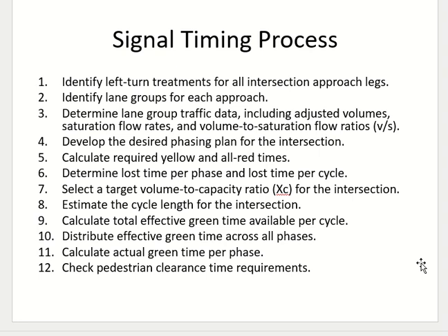If there are 2 lanes in one lane group, both of them have the same movement, which is in the same direction. So identify how many lane groups you have, and how many lanes with exactly the same movement. Then for each lane group, find out the demand, find out the saturation flow rate, and then take the ratio of demand to saturation flow rate for each lane group.